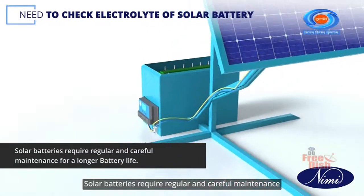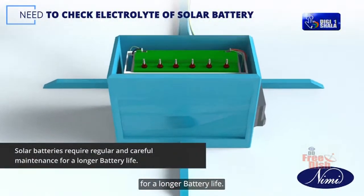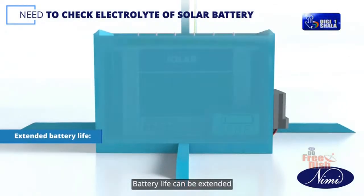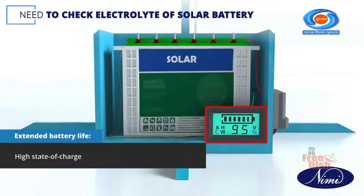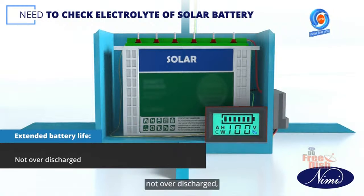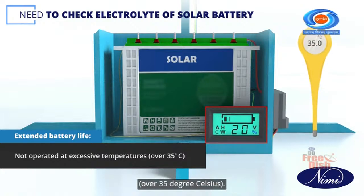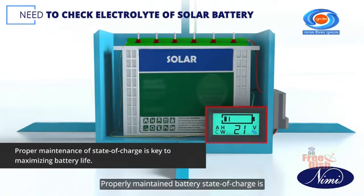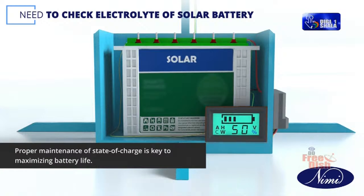Solar batteries require regular and careful maintenance for a longer battery life. Battery life can be extended if it is kept at a high state of charge, not over-discharged, or operated at excessive temperatures over 35 degrees Celsius. Properly maintained battery state of charge is key to maximizing battery life.